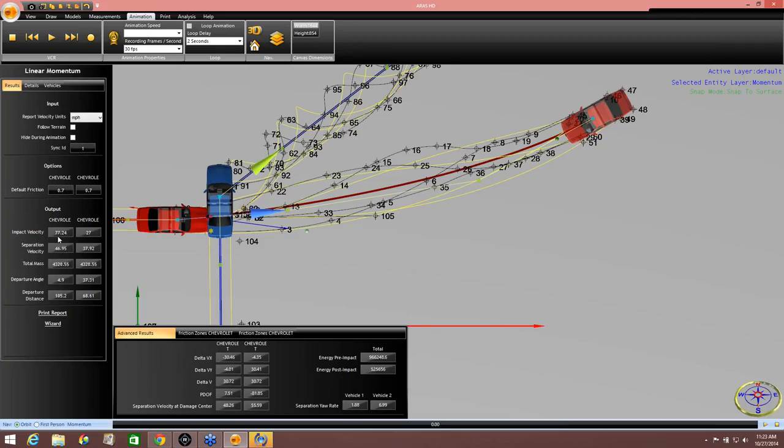So when I used a 0.42, I can justify that. Because ground friction is a 0.7, rolling friction on these cars was somewhere around a 0.2, I went right in the middle of it. Because you know what? Sometimes they were rolling and sometimes they were sliding sideways at the full friction. So I can justify using that average in the middle somewhere.